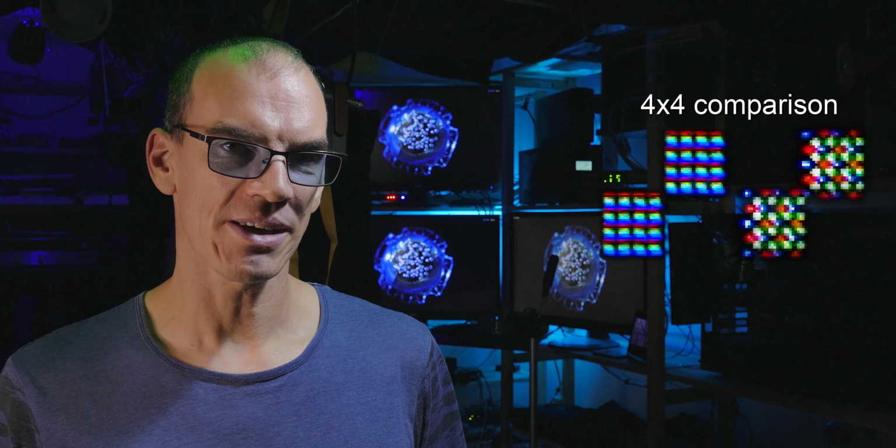So pentile displays have a number of pros and cons. One of the big ones is that because the elements are being shared between multiple pixels, the subpixels are not necessarily in a straight line. This can actually help reduce the screen door effect. They can be cheaper to manufacture because there's less complexity for a given resolution. If they're designed for it, they can be amazing at doing different resolutions that aren't necessarily multiples of each other on the same panel. Pentile displays can have better luminosity, and that's a bit more of an involved conversation, so we'll just leave it alone for now.